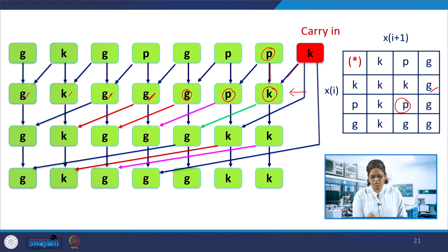So the stage 1, getting it from the 2 bits of the inputs A B, whether the carry will be generated at the first stage or it will be propagated or there is no carry. And after that, this uses the recursive doubling technique. And the next stage is copy.